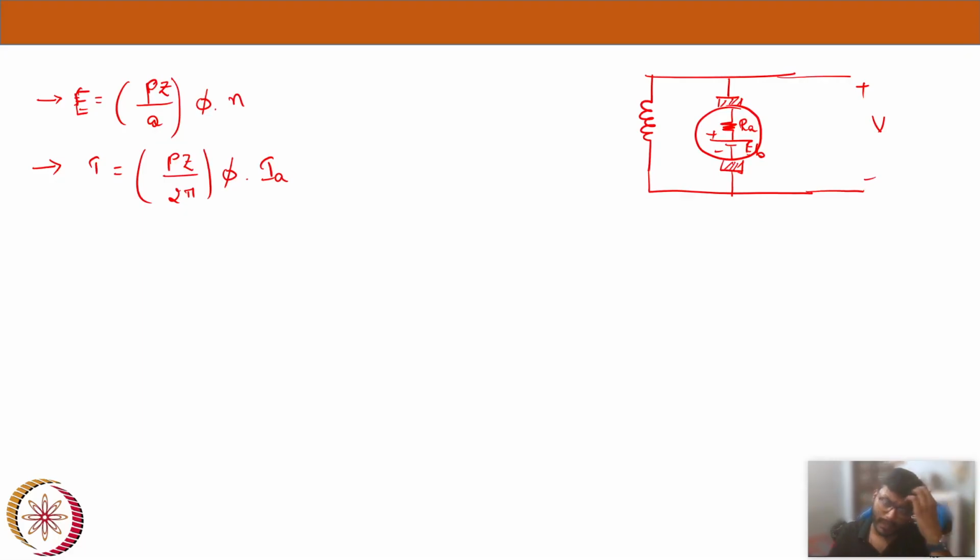Yeah, here the voltage across both the armature and the field winding is the same, and it is the same as the input supply. So there is no separate voltage like armature voltage VA and total supply voltage V. Both the voltages are the same. So input voltage V is the same as VA, which is the same as VF, that is the field winding. And this is RSH, shunt, because SH stands for shunt, it is also the field winding.